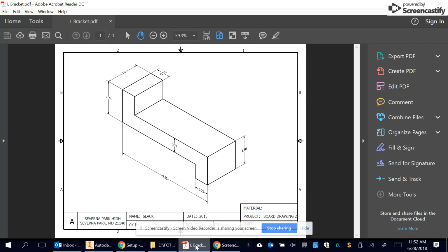So I'm going to look at my drawing here, at this bottom line right here. Notice that my dimension goes from the corner to the far edge over here. So I need to do a little bit of mathematical work, and I need to subtract this 0.75 away from the 5.25. If we do the math, we're going to get 4.5. So I'm going to draw this line at 4.5.